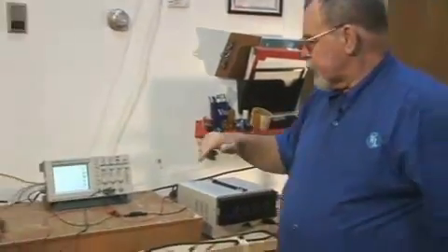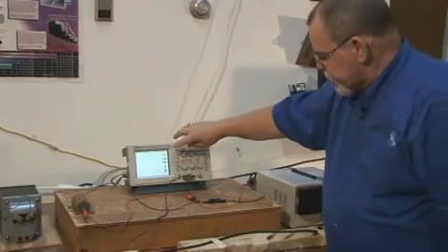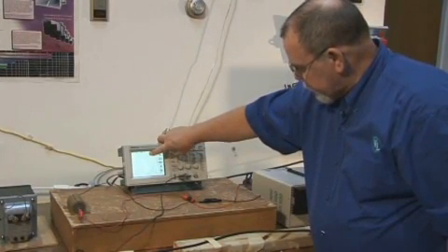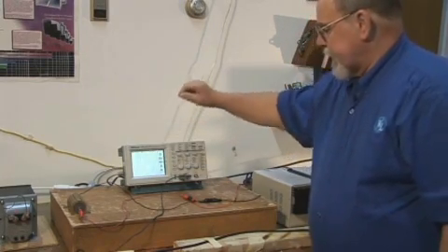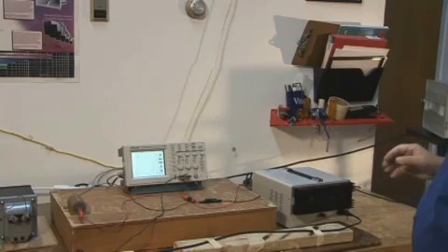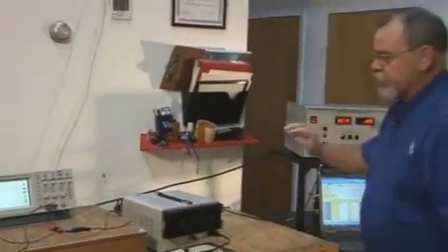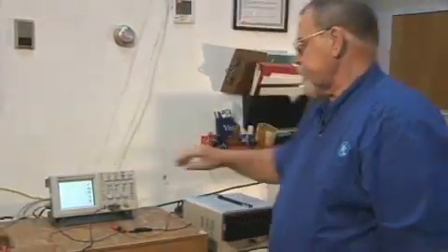And I'm starting to see this on the oscilloscope. At this point, I can see that I'm having a lot of trouble trying to see my applied voltage. This is occurring by that you can see the peak amplitude of this waveform varying ever so slowly. And that is what the interfering signal is doing. I'm going to turn the output level down again just to show you on the oscilloscope that that movement disappears, and then becomes a very stable signal.